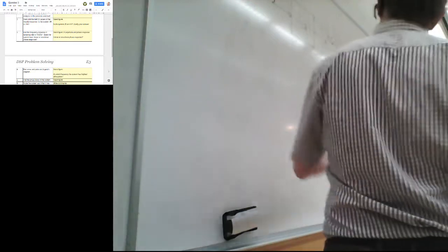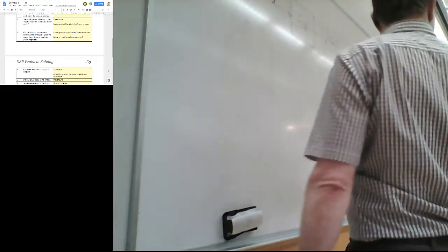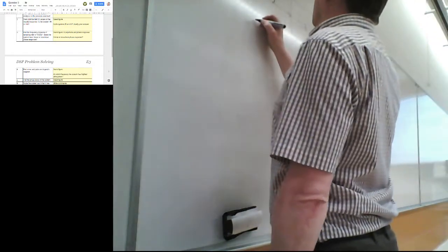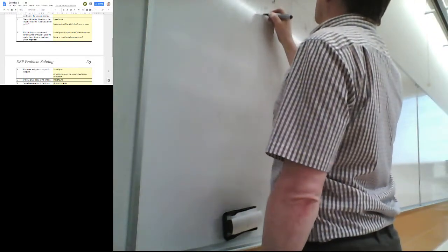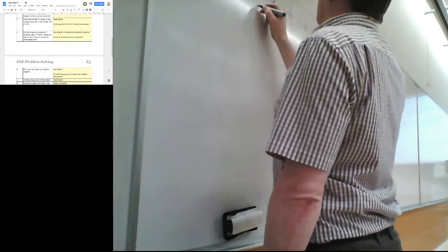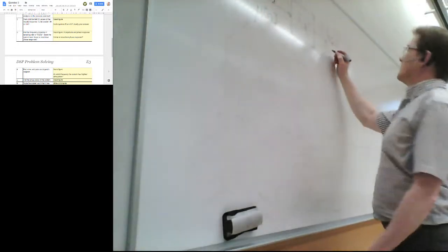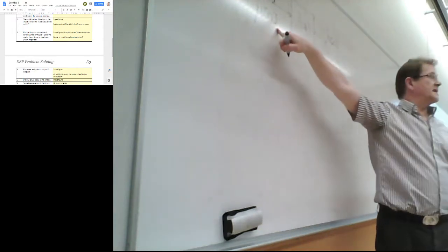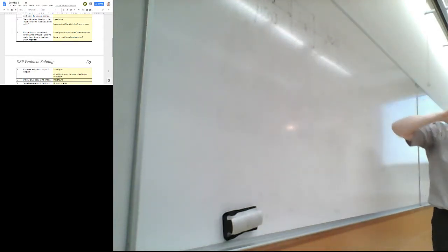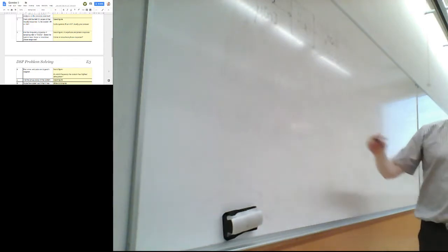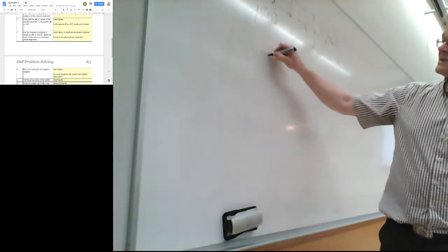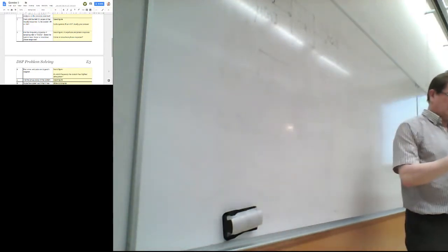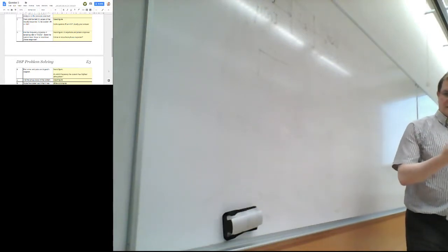In case you have an analog system and would like to test it in digital domain, then you would do step response by running the unit step input to the system. So basically, function generator gives this nice edge that you can use.